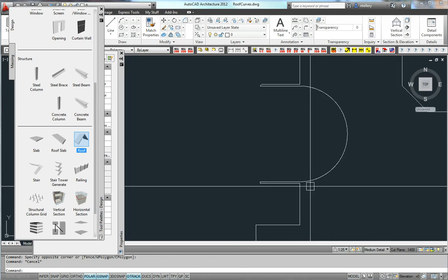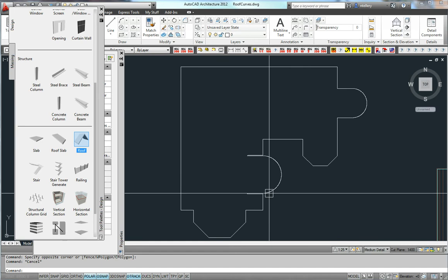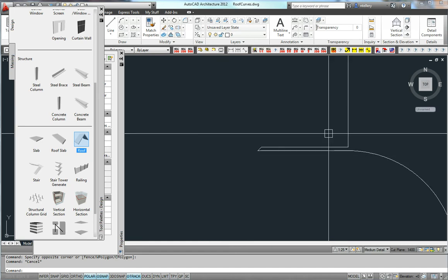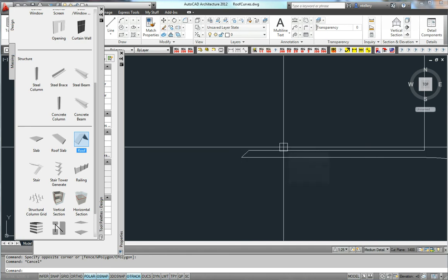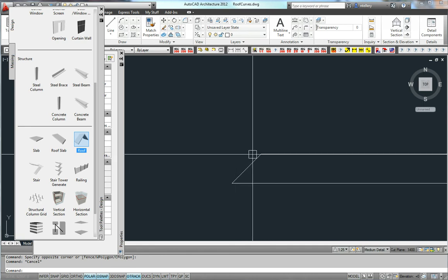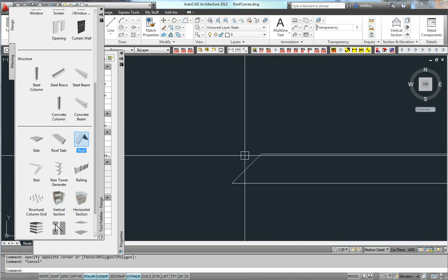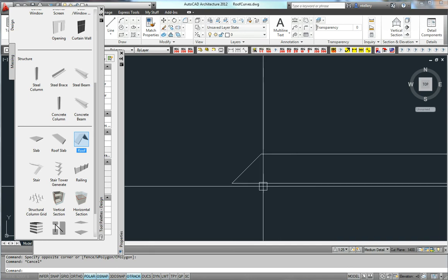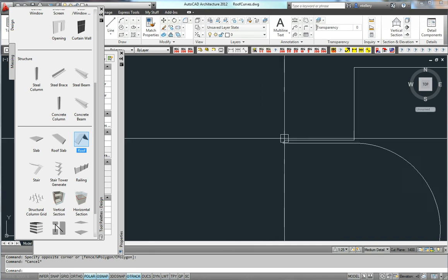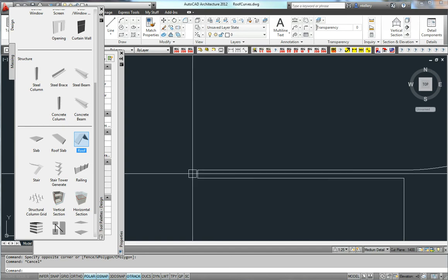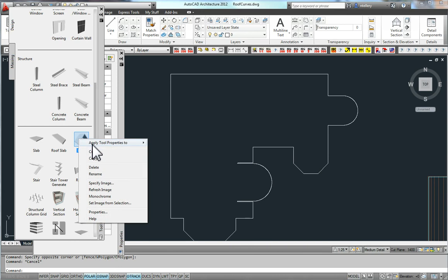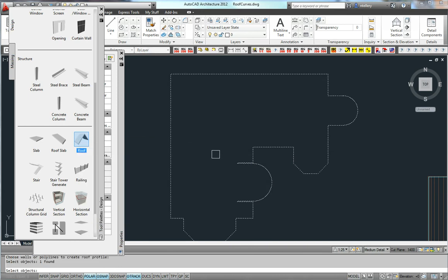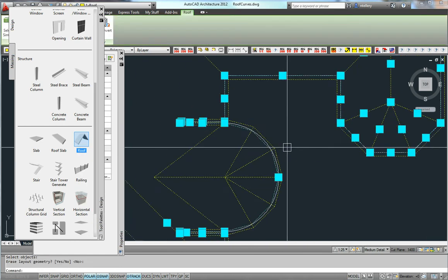And if you watch the earlier videos, you'd have an inkling of why I've done that. I've done it a set distance. I do that so then I can stretch the back part, that would normally be this when you're drawing it up. I can stretch it back so this distance is a nice isosceles triangle. You can see I haven't done it here, so I'm going to show you what happens there. Oops. Apply it to line work, pick the line work, and voila.